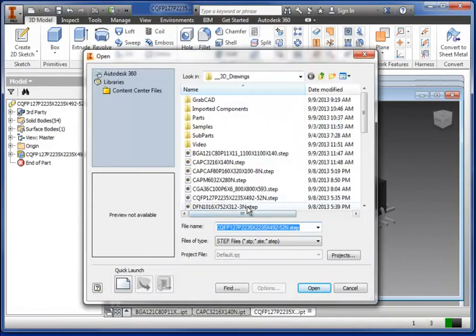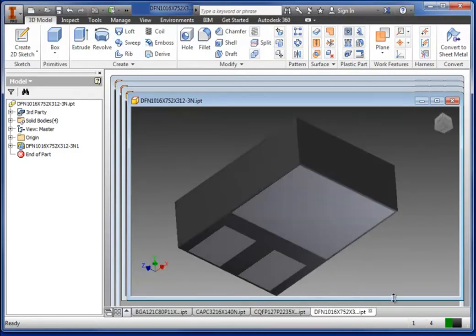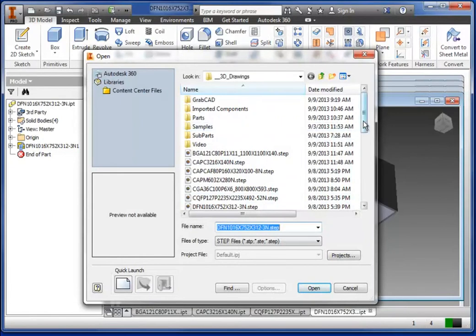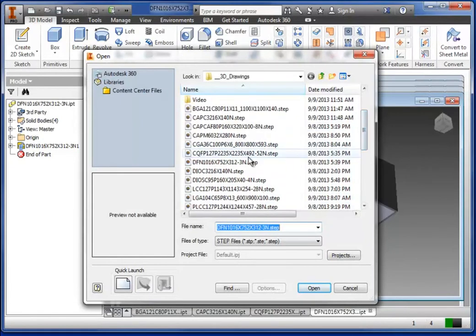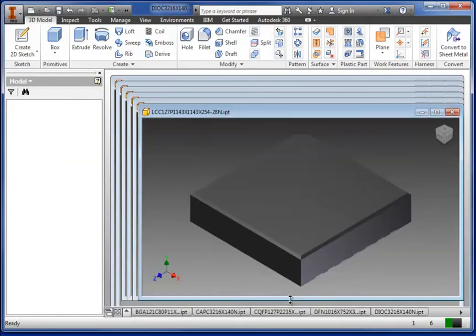orientation. Next, let's bring up a DFN part with the different leads, sizes, and widths automatically generated, matching the PCB footprint land pattern model, which we exported to Allegro or a host of other EDA tooling systems. Selecting the diode part, notice that the user-defined color code is red. And bringing up an LCC part, notice the automated corner chamfer in the upper left corner matches the original datasheet